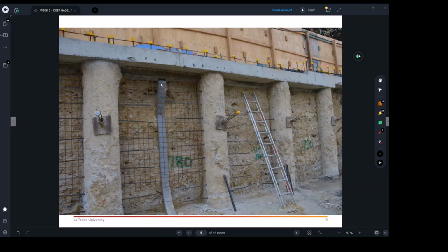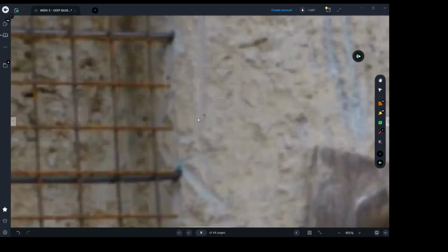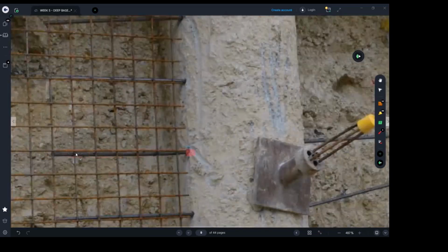So what we do, we put this drain strip, and it's typically going to be between each 2 piles. And if there was a water level rising behind that wall, it will all be collected by this drain strip and then connected to the stormwater system, right? So we put this first, then we put the reinforcement, the mesh for the shotcrete wall. Then we also have to drill some bars. These bars are drilled with epoxy, so we drill, we put epoxy, then we put the bar.